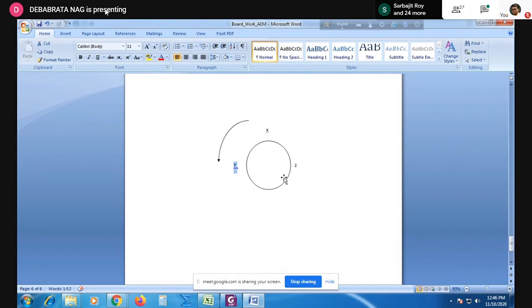That will be equal to minus iyz into omega dot y and then plus ixy omega y square. I say again, summation maz becomes equal to minus iyz into omega dot y plus ixy into omega y square. So these will therefore be your three equations of motion in the case when your y axis becomes your axis of rotation.